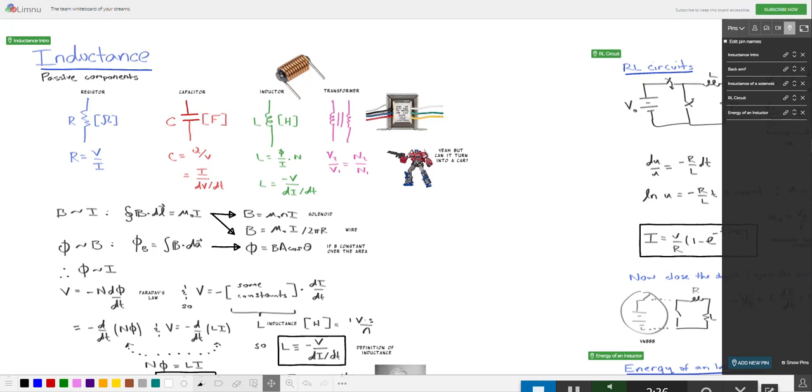All right, so how do we come up with these relationships? I want to talk about that for a second. First of all, we have to know that flux is proportional to current. And the way we know that is we know that flux is the product of area and magnetic field, and magnetic field is proportional to current. To convince you of that, I've just written Ampere's law, and we've seen this before, but I'll derive the magnetic field in a solenoid again a little bit later.